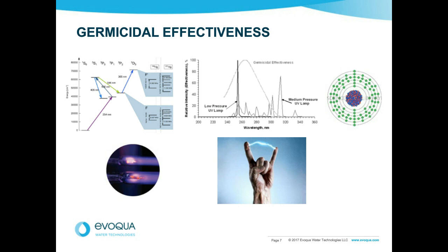I think the microelectronics industry make very, very high quality water. They use lots of UV for TOC destruction, for disinfection. UV works very well to deozonate water, and it works very well for some of the more bizarre fluids like the brines, the marinades. As we start to see these heat-tolerant bugs propagating and proliferating, then more and more UV will be used by the tea manufacturers and the non-alcoholic carbonated soft drinks companies who want to extend shelf life and keep their products safe.